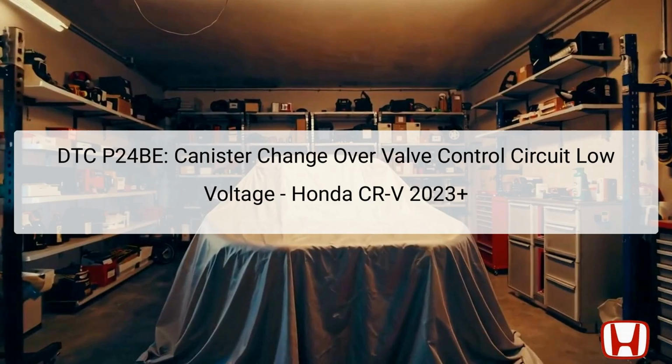The Powertrain Control Module, PCM, monitors the valve's operations and responds by altering functions to ensure optimal vehicle performance. A low voltage reading suggests that the PCM detected a problem when no signal should be present, which can disrupt normal operations, potentially leading to fuel system issues or increased emissions. This guide will provide a comprehensive troubleshooting process to identify and resolve the DTC P24BE error.